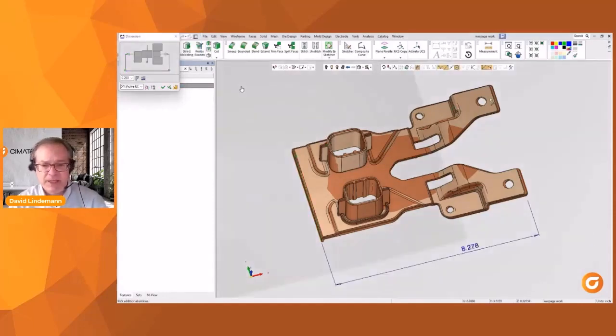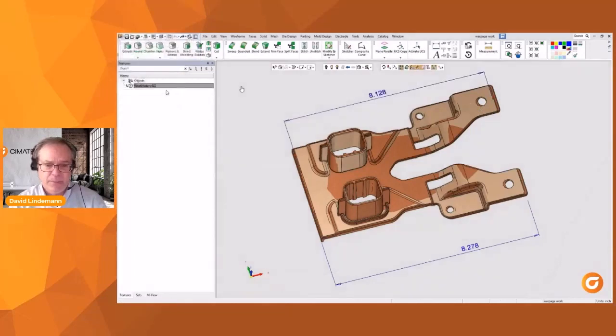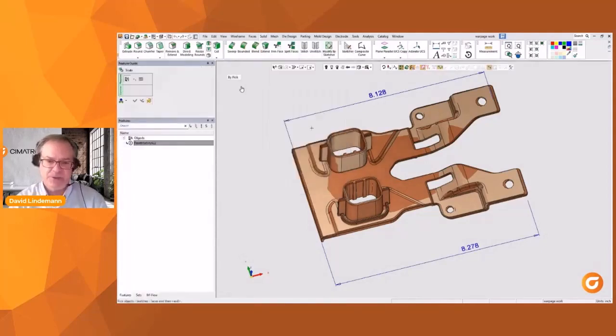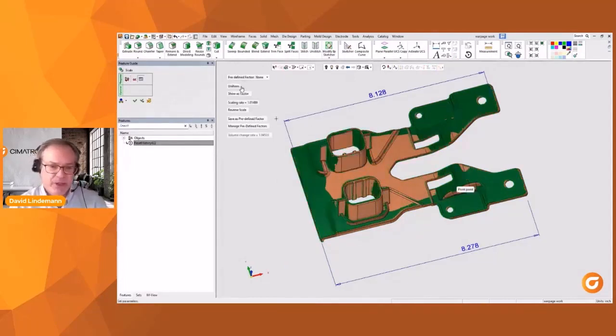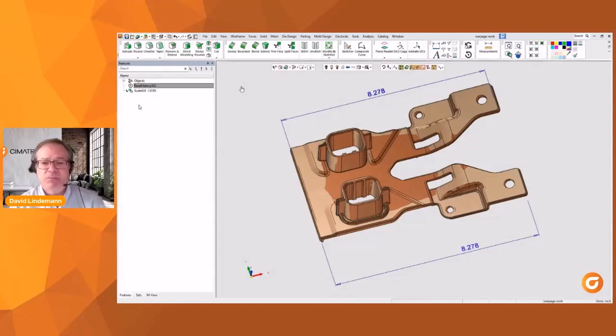So there's my first PMI on the STL file, and I'll find exactly the same other dimension here on the CAD file. And I've got something to compare it to. Looks like I've got that reversed. I did the CAD file first. With these two dimensions, though, I just simply divide one by the other, and that gives me the equation to know how much the shrinkage, that shrink factor, is involved. And from there, I can now expand the STL, scale it, so that it matches what's happening with the part. To get super specific, we can do it differently in the X and Y direction, Z direction as well. All right, so now I'm fairly confident that those parts are much more even in size, minus our shrink factor.